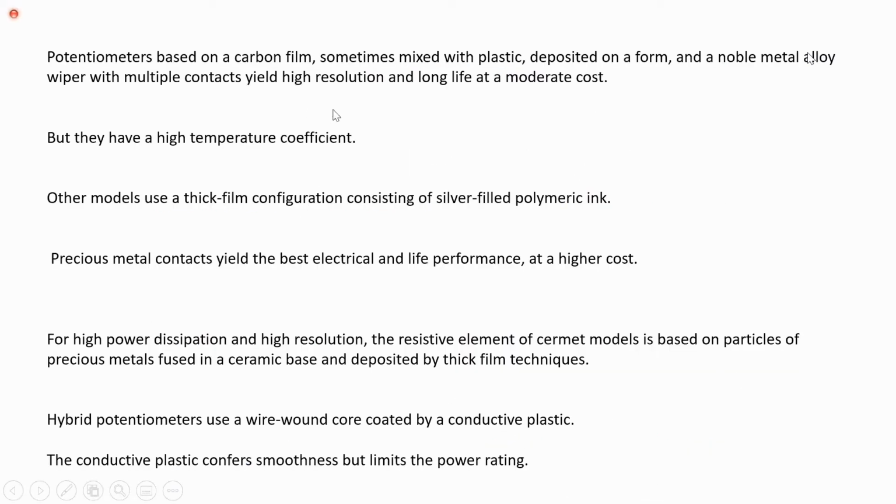Potentiometers based on a carbon film, sometimes mixed with a plastic deposited on a form, and a noble metal alloy wiper with multiple contacts yield high resolution and long life at a moderate cost. Students, if we paste our resistance on carbon film, it becomes a chemical type of potentiometer, but they have a high temperature